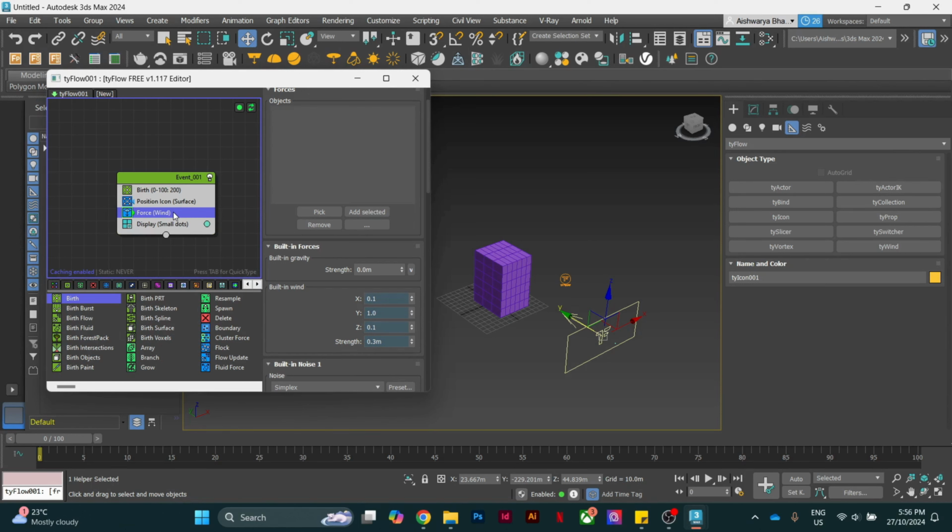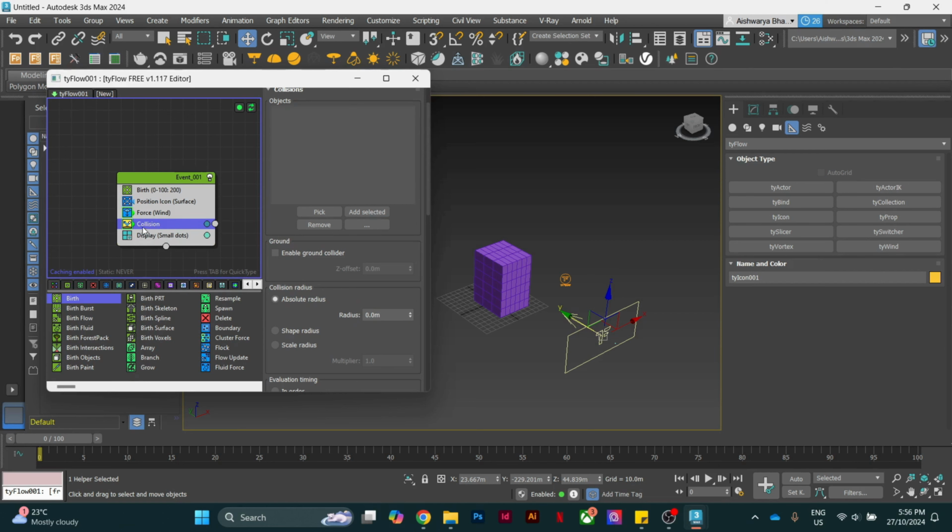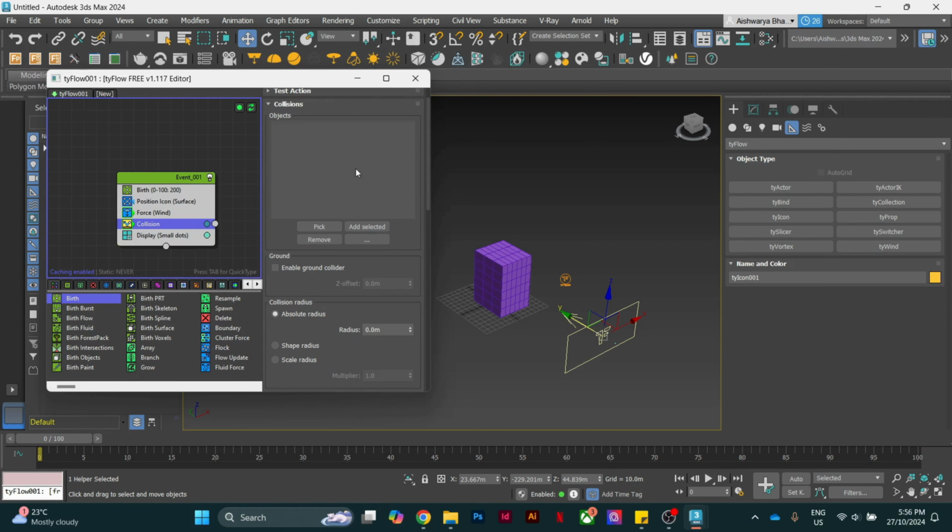So click on force, tab, and write collision. Just make sure it is at the bottom. Yep, so you just have to pick which object it's colliding with. And for our example, it will be this object right here. So we pick and click on our object. And now if we can see some of our particles, the ones that are touching our building are not going through it. They're going either up or working their way sideways.